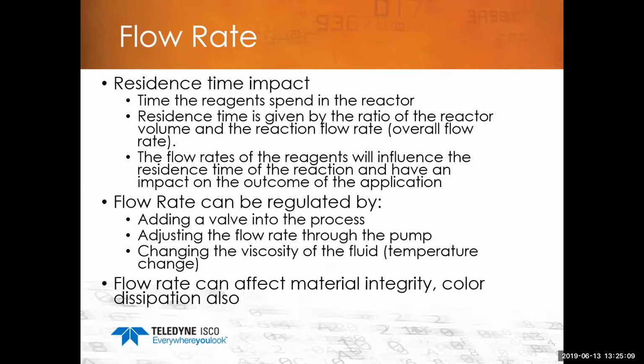Okay. In the plastics world, the flow rate can affect the color dissipation. When you're looking at an extrusion process and you're dosing chemical colors or UV chemicals into the extrusion process, you need a uniform color for the most part. So you have to have a very precise pump and account for either the pulsation or eliminate it.